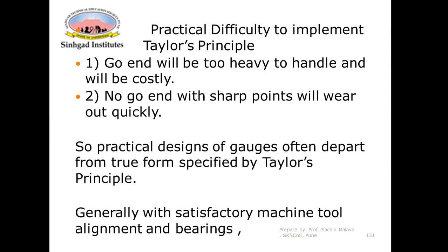But whatever Taylor's principle we have discussed, there are some practical difficulties to implement it. What are those practical difficulties? If we make the go end equal to the size of the hole which we want to check, then the go end will be too heavy to handle and it will be costly also.